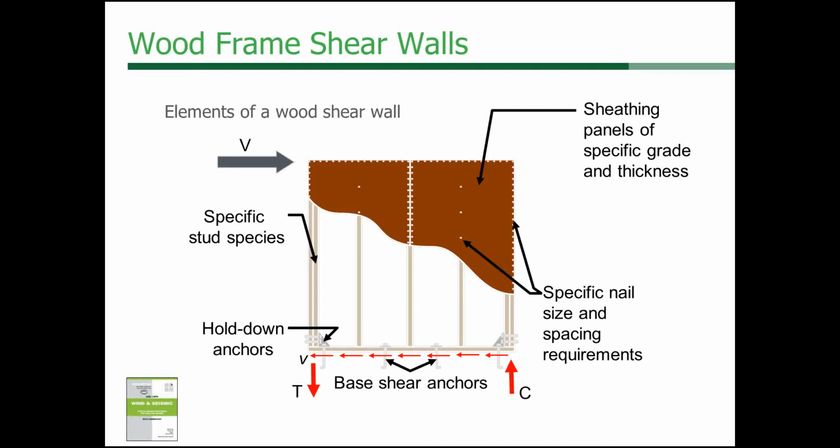that performance. You know, we always say, oh, well, the finishes are going to help it perform better, but until you test it, you're not going to be able to really provide factual information on that. But there is better controlled performance at those narrow panels as well, and it also showed that it exhibited shear behavior, which was evident. You couldn't see it because it wasn't in the video, which was evident with the diagonal cracking of the stucco in that area.